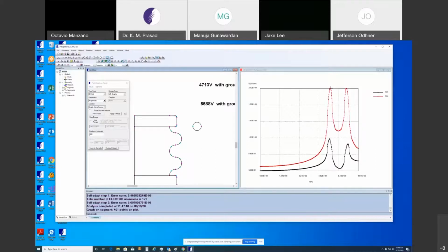This is 2.12 kV per centimeter. The black curve is when this is 10,000 volts and this is also 10,000 volts. Then you have approximately 1 kV per centimeter. When you have just an aluminum ring which is not connected to this, then the fields have jumped almost double, slightly over double. This is understandable because when you have 10 kV here, 10 kV here, what will happen?